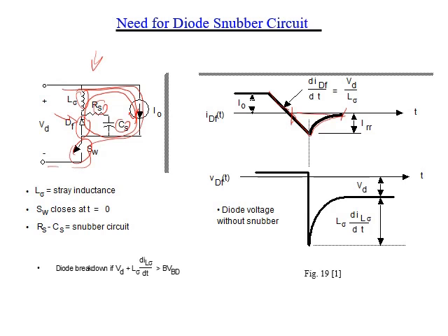This is called time t_rr, the reverse recovery time, and the peak of this current is I_rr, the reverse recovery current. This is when we have a snubber circuit. Without a snubber circuit, the current will go higher than this, and when it comes back, it will not return to zero. There is voltage to be blocked here. So how do we protect this diode?